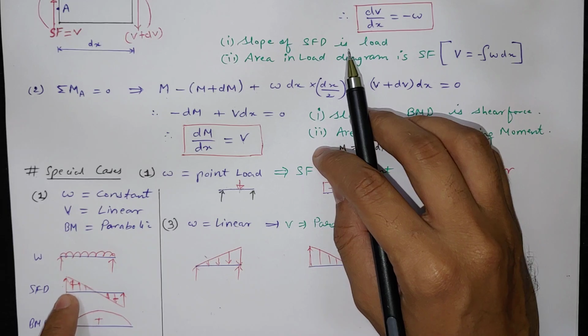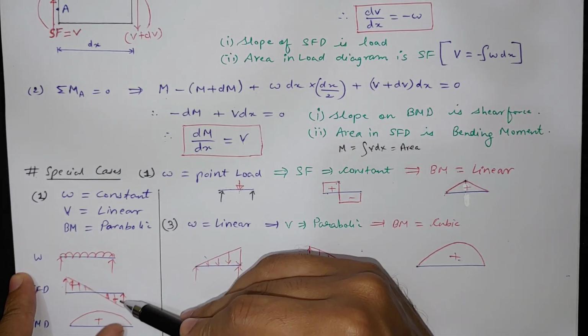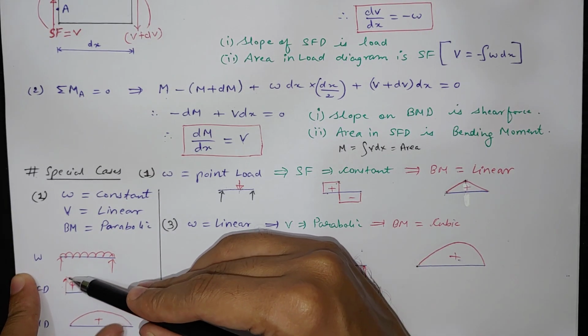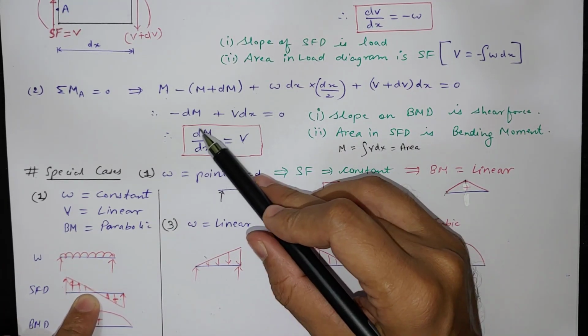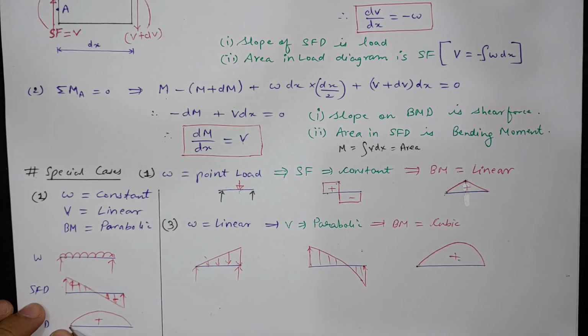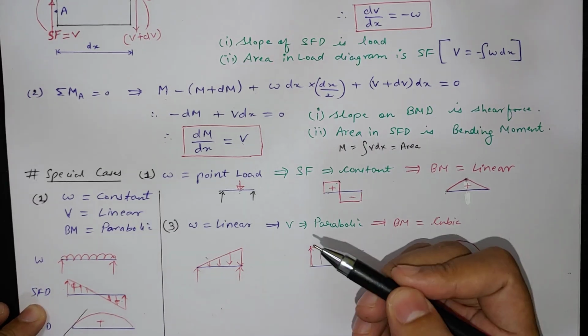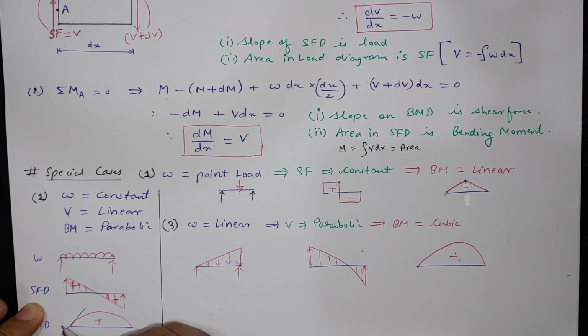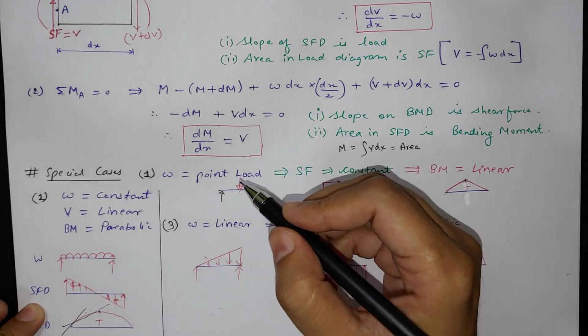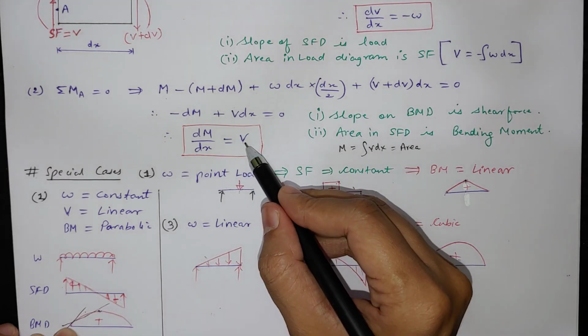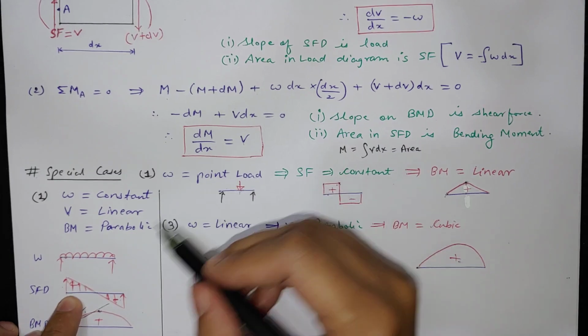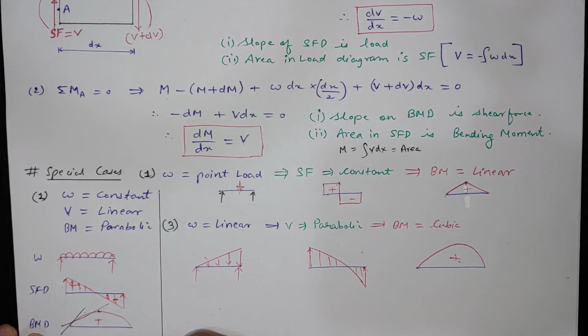Now on this side it is positive, on this side it is negative. Here it is positive but the value is decreasing, so the shear force value is decreasing, which means the moment diagram slope value is decreasing. So the slope is this initially, afterward it gets slightly reduced, and finally at this point the slope is 0. So the slope value is constantly reducing because the value of shear force is decreasing, and it is in positive direction, so all positive slopes.